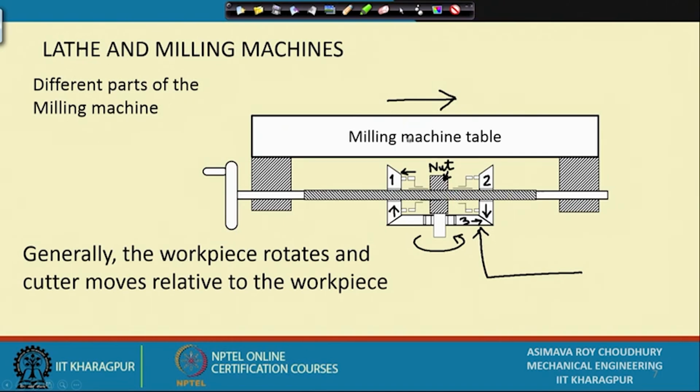But if I rotate the milling machine table about a vertical axis, won't the screw run out of contact with these? No. As we noticed before, these will simply shift position out of the plane of the paper, but they will still remain in contact with the prime moving bevel gear number 3, because they are going round, they are not coming out laterally outside the plane of the paper. They are going round on this particular bevel gear. So, always they remain in contact.